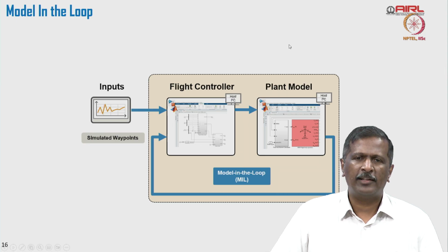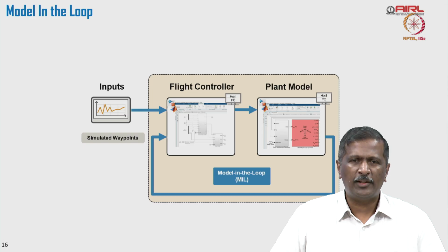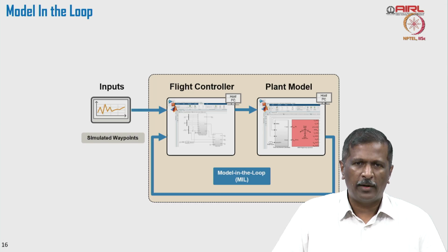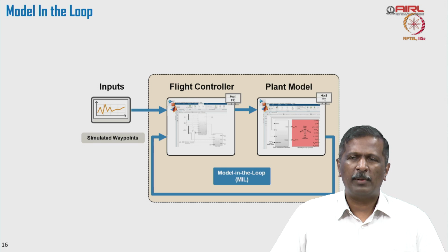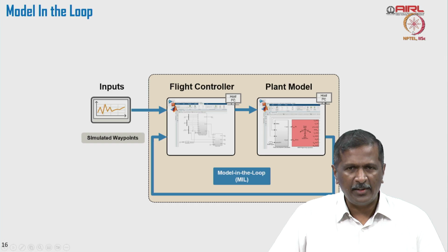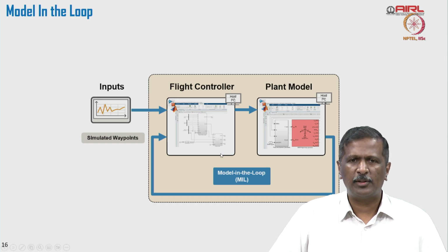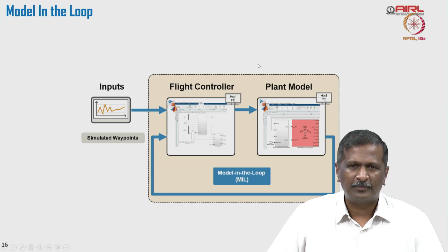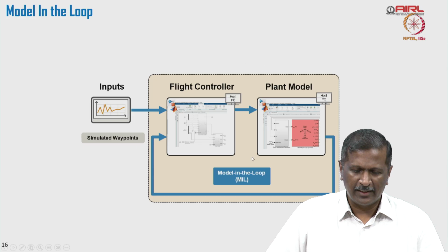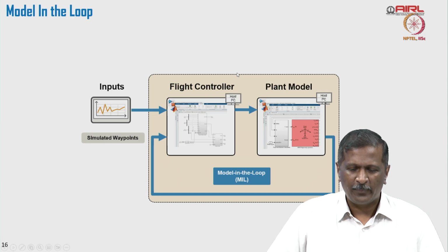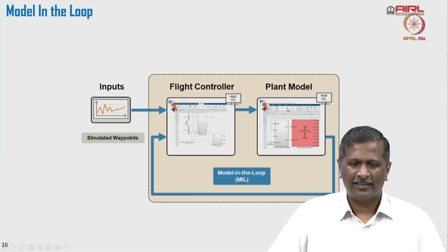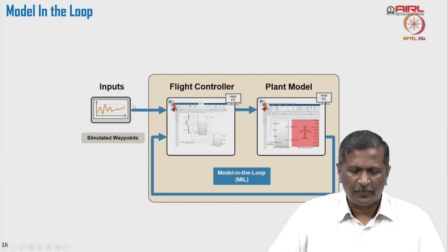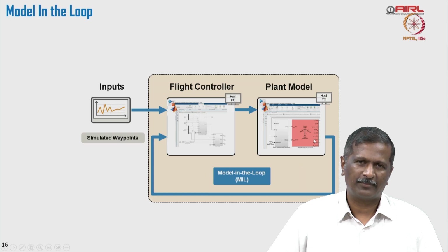This is very important for our course. When we talk about obstacle avoidance, global planning or local planner, we only talk about those as input, and that will generate a trajectory, and that trajectory is given as an input here to the model. Can the model follow the input accurately or not, right? If you see, till now, till module 4, we talked about plant and control, right? This is taken care of. This particular plant receives the trajectory. Can it follow the trajectory? Okay.